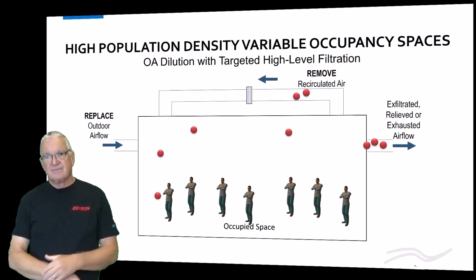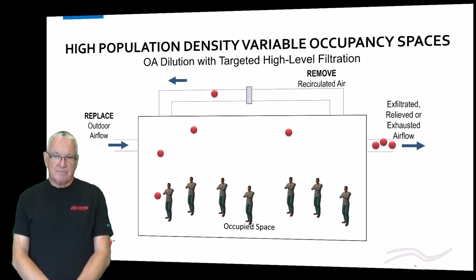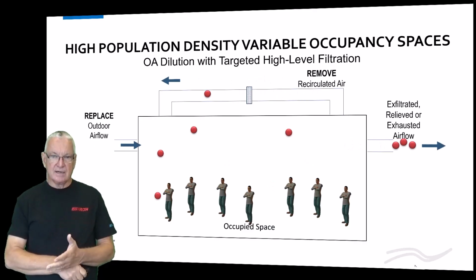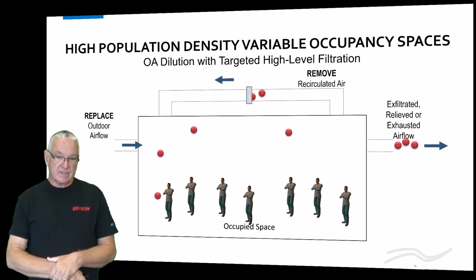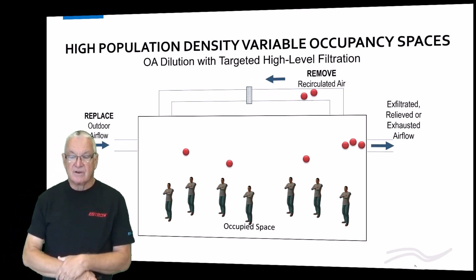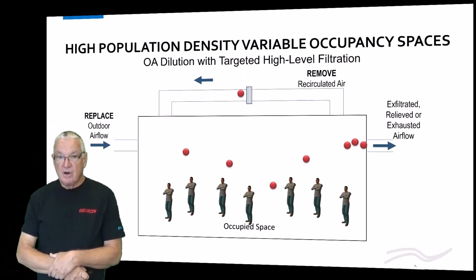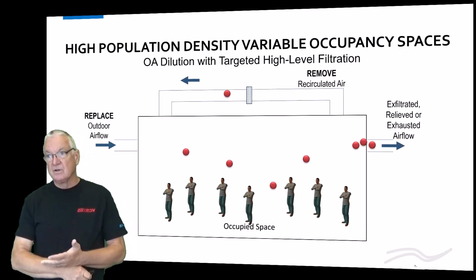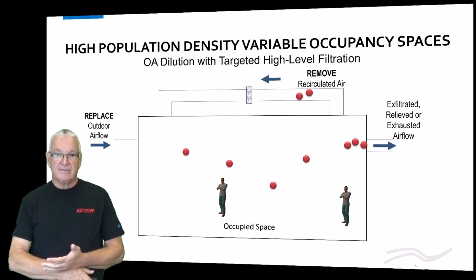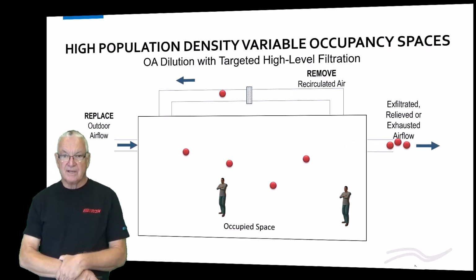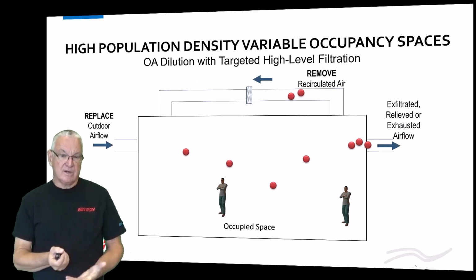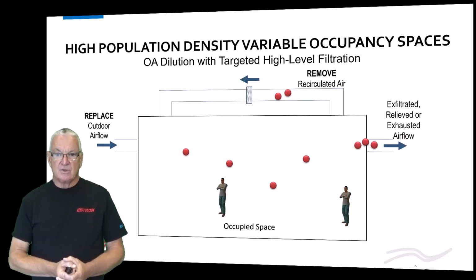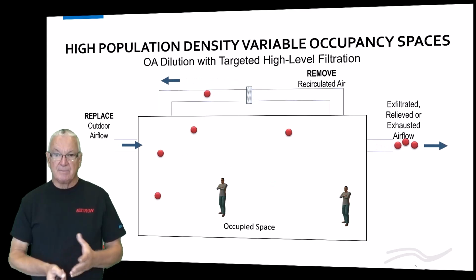All right, first of all, the basic deal here is this. Demand controlled ventilation does make sense. A lot of the outdoor air is required to dilute contaminants and body odor from the occupants, and it's very much related to the occupants. So if you have a higher occupant density space that is full, you have one ventilation requirement. And then if that space goes to a much lower population, then you have a lot less outdoor air required. So it makes sense that you would want to reduce the outdoor air and not bring in the design outdoor air when the population's variable.